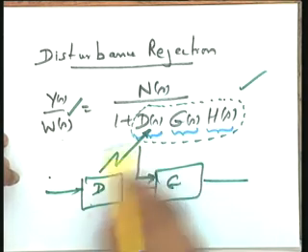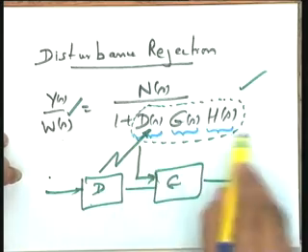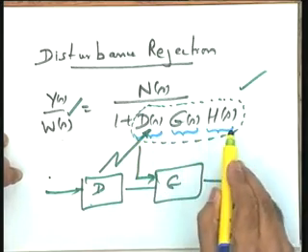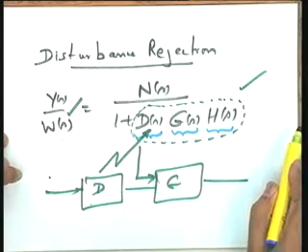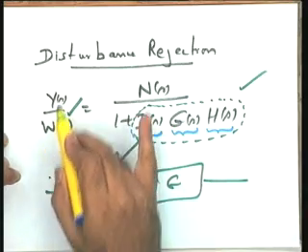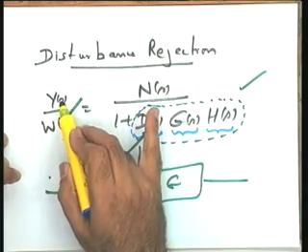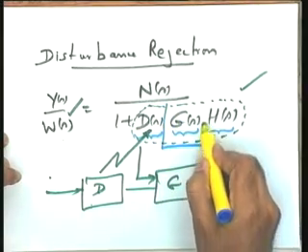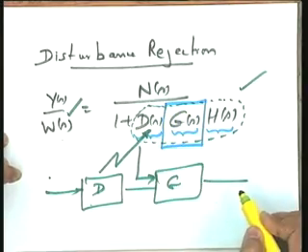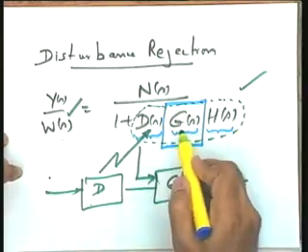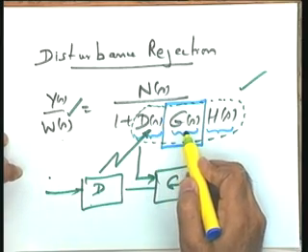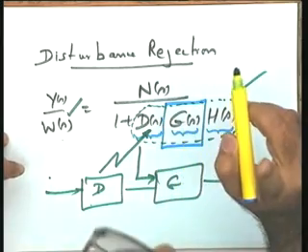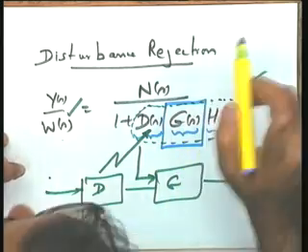You will actually change your D(s) so that the loop gain D(s)G(s)H(s) is increased, and hence the disturbance effects can be filtered out. Now one thing to be noted, suppose somehow you can change the gain of G(s) also. The loop gain through change in G(s) can be increased, no doubt. But one point may please be noted, you have to be extra cautious about it.